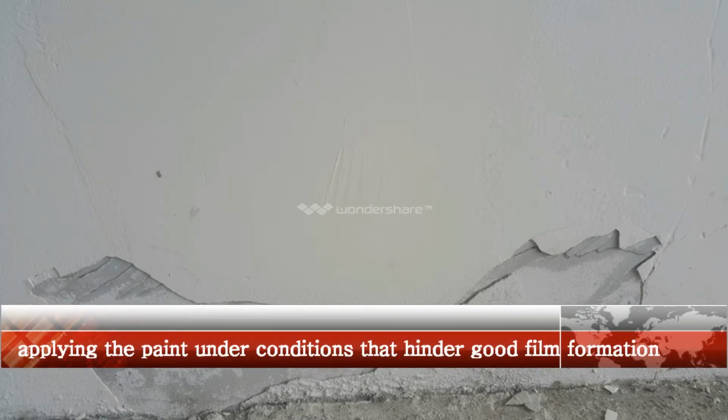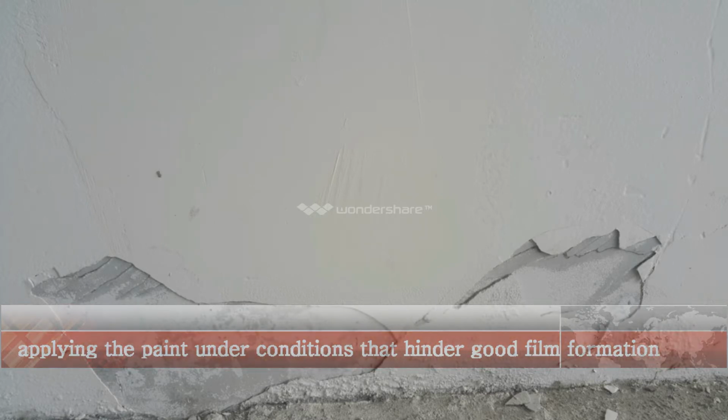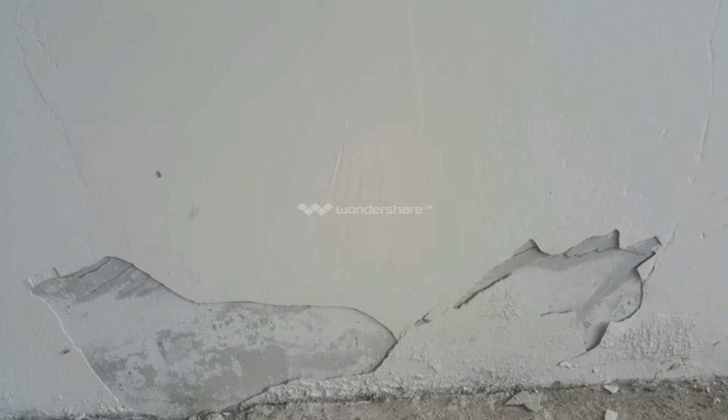Peeling can also be caused by applying the paint under conditions that hinder good film formation: very cold weather, or very hot or windy weather that causes the paint to dry too quickly. There are several possible explanations for a paint job that fails due to peeling.